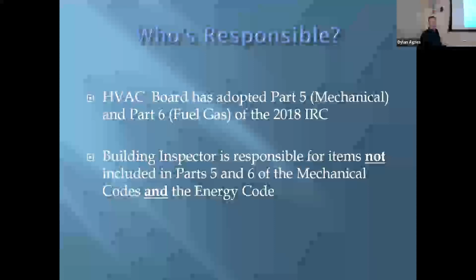But the masonry fireplaces have structural elements. And so in a lot of cases, we have different people looking at different portions of it. And this is also a reminder that anything related to the energy code is under the authorization of the building inspector. He may have his mechanical, his HVAC guys looking at it, but it's still his primary responsibility.